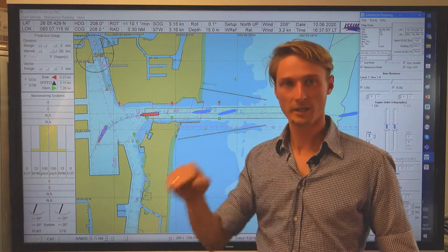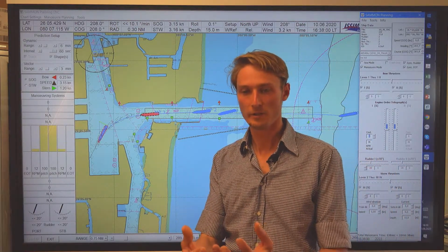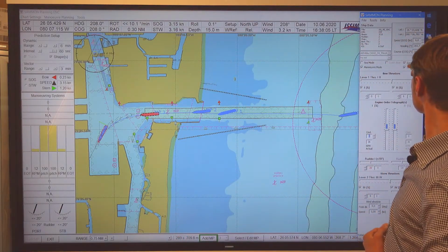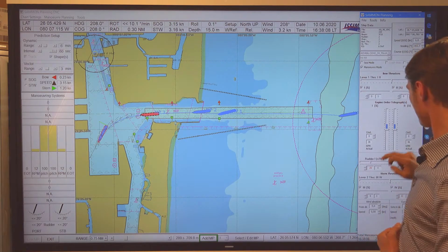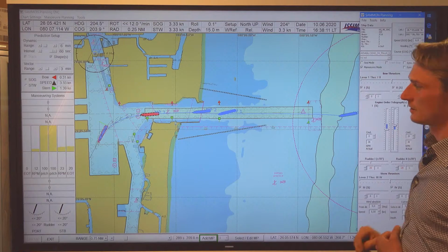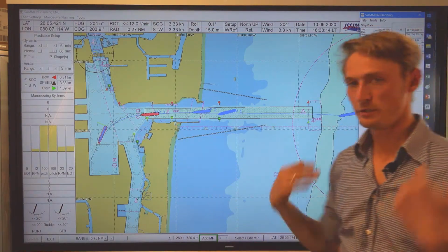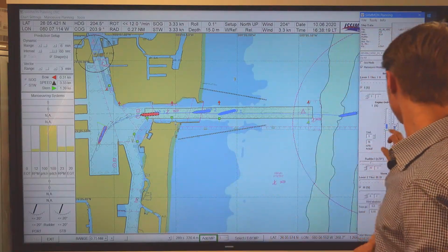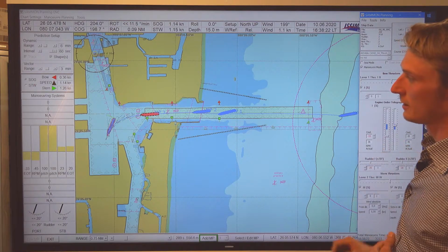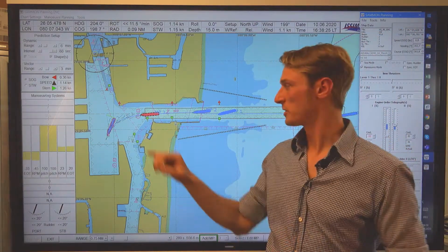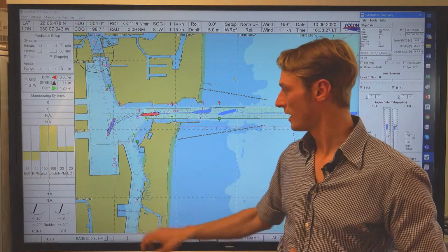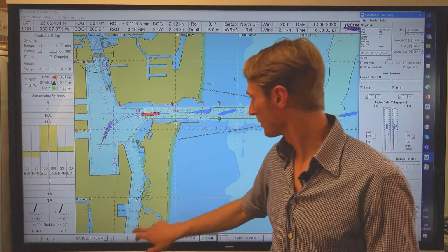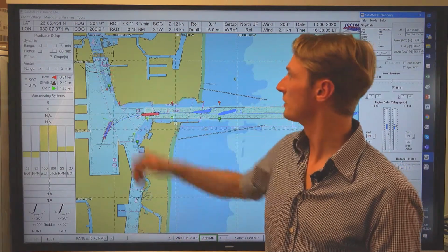If I now keep one engine running ahead, of course I also have the inflow, or the wake, from the propeller itself. So let's split the engines and give on starboard side a command ahead. And on port side, using the shoulder effect, I can pull my port shoulder back. My starboard shoulder is running ahead, port astern. It is shortening the turn, so the speed is dropping quite fast, and I have a higher rate of turn in order to reach this final position where I want to change to the starboard wing and continue my maneuver.